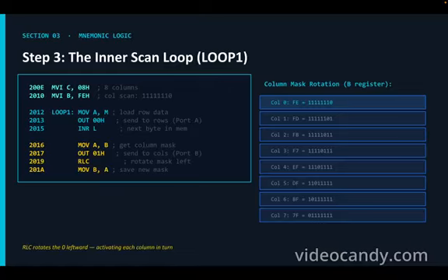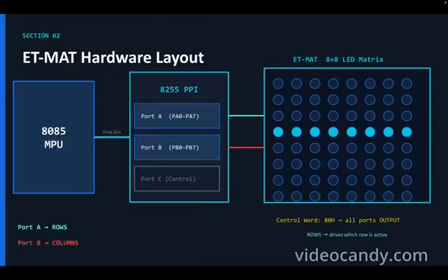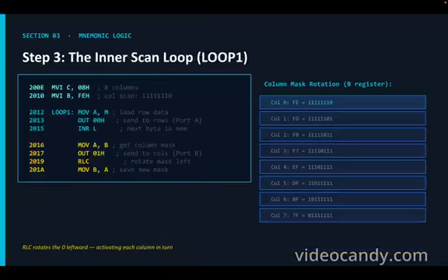So for using my LED interface, what I need is the rows to be 1 and my columns to be zeros. So when I input 7 ones and only 1 zero, only one of my columns is going to brighten up. When my value is FEH, only one of my columns will brighten up, and all other columns have logic 1, so they are inactive.